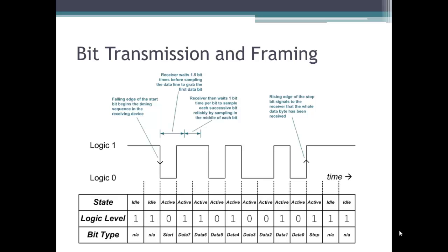The way this scheme looks, if we look at an example waveform, an example message transmitted, we can examine the data bits and the framing. What we're looking at over here is an example waveform as time goes on. All the way on the left of the diagram, we can see that before transmission begins, the TX pin of the USART peripheral idles high.